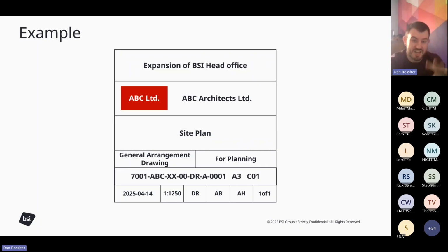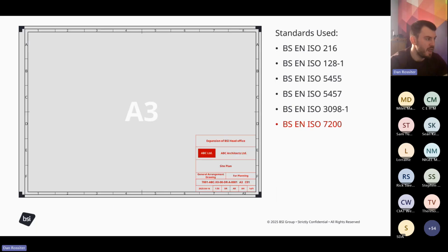So you can arrange it in any way that you see fit. They can also be long as opposed to being tall, so it does provide guidance, and that standard even gives you some examples within it showing different layouts and different versions that conform to the standard, which is quite useful. So sitting that in there on an A3 drawing, it takes about this much room. As you can see, it's sat there nice there in the bottom right corner.